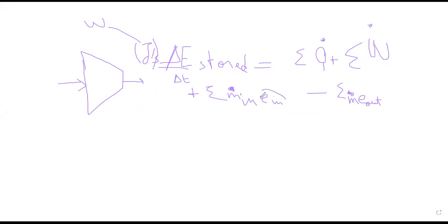This is what we call the internal energy. And the internal energy is decomposed, or this is the energy, sorry, the total energy of the particles coming in and getting out. So this energy is decomposed into several parts. You can write it as internal energy plus kinetic energy plus potential energy, etc. In the majority of mechanical equipment, turbines, pumps, the variation of internal energy is dominant over kinetic and potential. This is why in several problems they tell you to neglect the change in kinetic energy and potential energy.